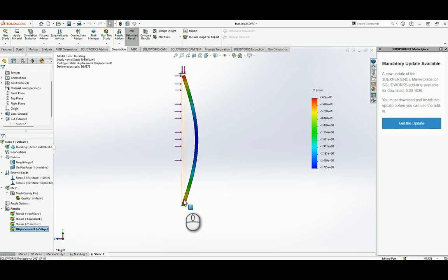Now if you were to plot this deflection at every point, we are supposed to be able to get back that deflection equation that we defined in the notes for V. If you go to page 28 of the notes, we have V equal to a whole long equation. That equation for V is supposed to correspond to the V over here. So if you were to plot finite element versus analytical, they're supposed to have a very small error, because we saw how well the maximum correlated with what we actually calculated.